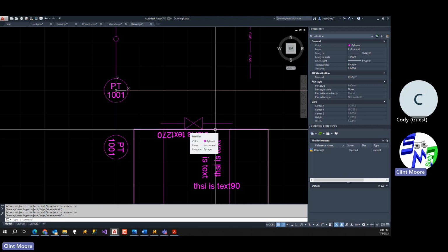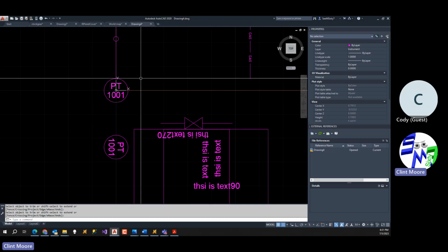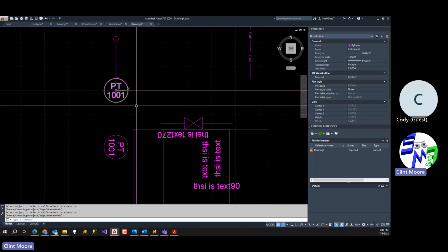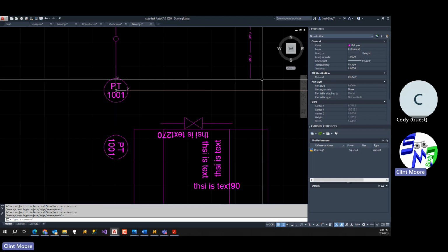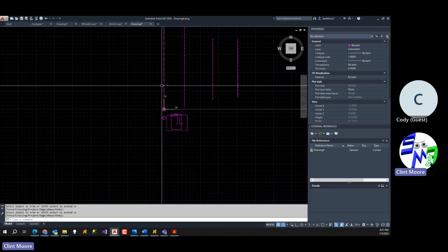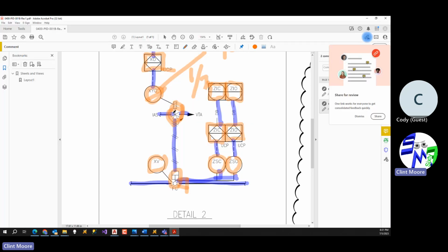Now, block sizes and things like that depend on the software you're using, but typically the instrument level is going to be very standard. Valves, this may be a little bit big for a valve. It might not be quarter inch, might be 3/16 of an inch, and then it'd actually be a little bit smaller valve. You have different valve sizes on a drawing as well. Okay. Sometimes the solenoid valve is shown a little bit smaller. Sometimes the main valves are shown a little bit bigger.